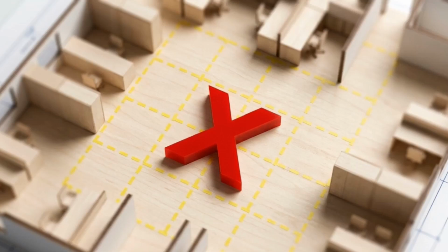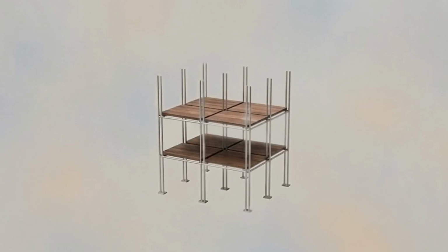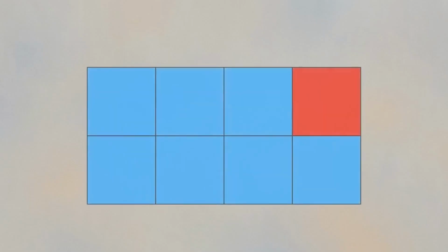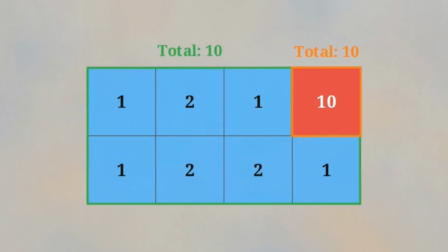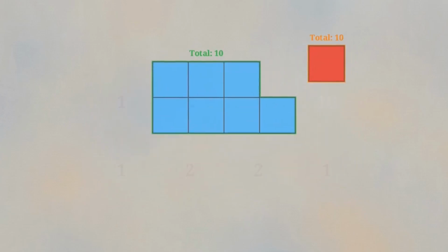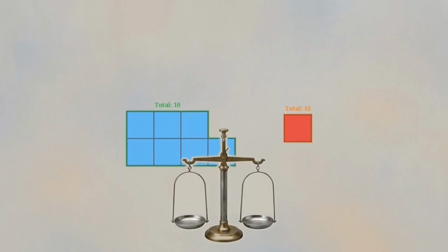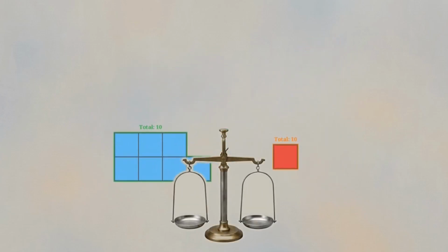To build a true Takt plan, you don't just slice a floor plan into equal square footage. You analyze the work density on a scale of 1 to 10. Highly dense areas, like a bank of bathrooms or an elevator core, get smaller zone boundaries so that the total level of effort or time required matches the rest of the project zones.